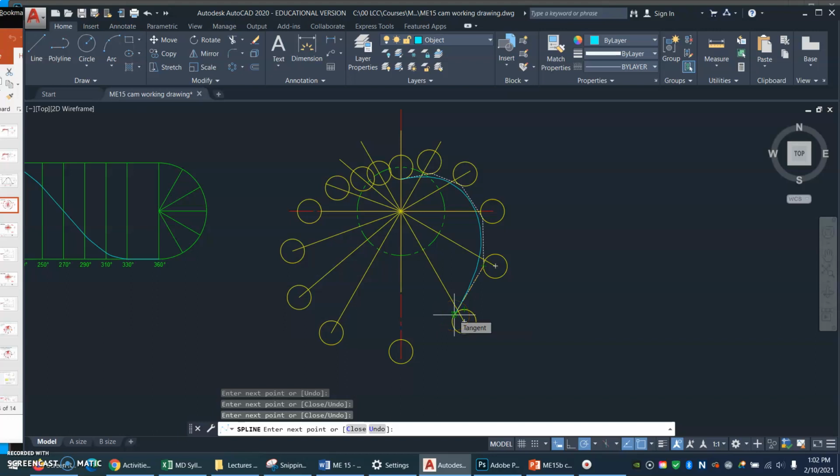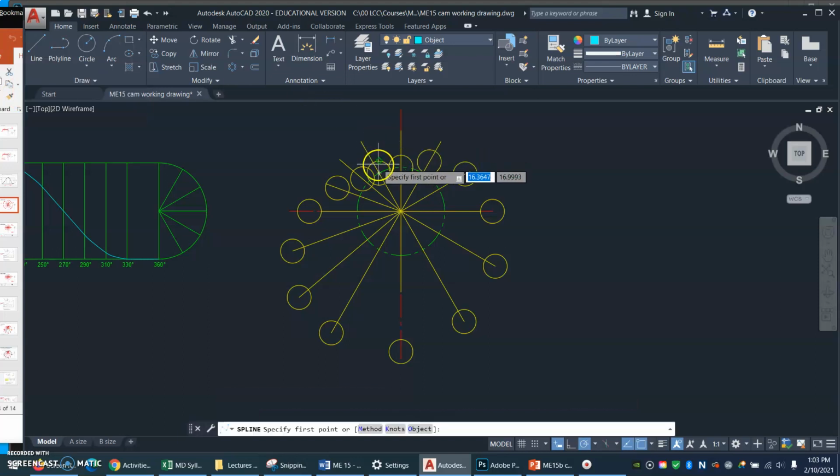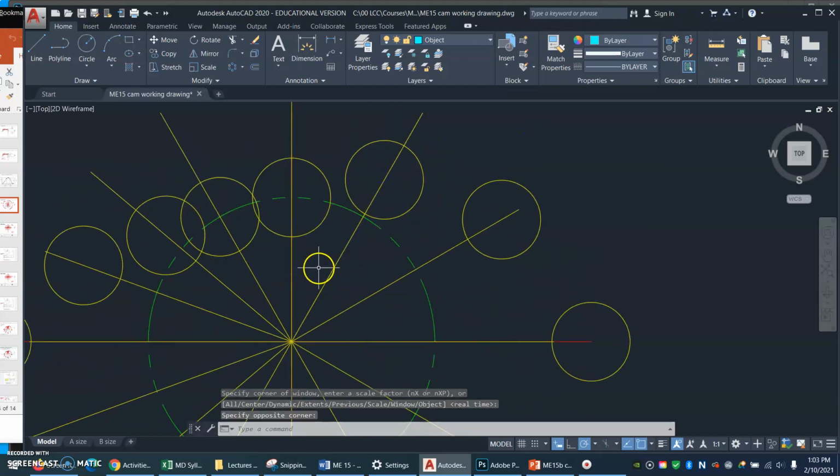But if it doesn't, now you can see what that spline with control vertices does. See, that's not what you want. The points are out in space, but the visible line is not. Okay, I was right. So we want this version of spline that has points on it. And we're going to go tangent, tangent, tangent. I'm going to go Shift, right mouse to bring up this temporary menu so that I can get, oh dear, sometimes it's a little bit cranky.